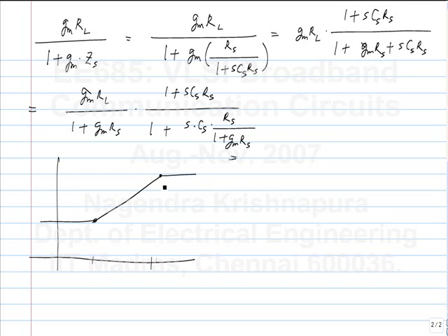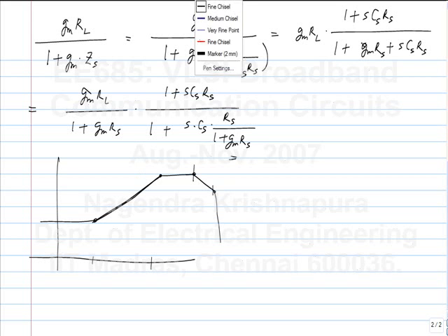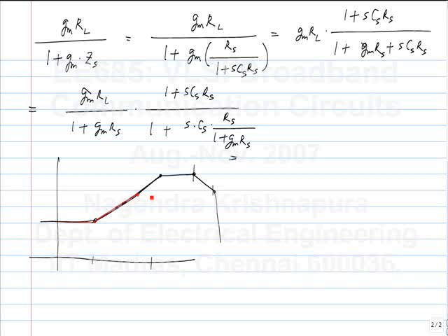And in addition to this, because of all the other parasitics, the gain won't be like this. It may fall off at higher frequencies. And if you are talking about particularly high frequency circuits, these frequencies can be inside this range of boost, so that you don't get such a high boost. Maybe you will get something like this, but because of parasitic poles, it tends to fall off already. But there is a range of frequencies that you get a boost at.